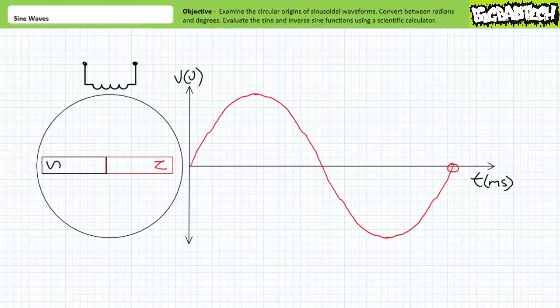The point being that the very act of generating voltage has its origins in circular motion, and no wonder the resultant voltage output is sinusoidal in nature. Additionally, we'll learn in later lectures that given sinusoidal voltage input, output current is also sinusoidal in nature for passive electronic components like resistors, inductors, and capacitors. In summary, everything is sine waves from this point on, and you've got to know how sine waves work if you wish to succeed in AC circuit analysis.